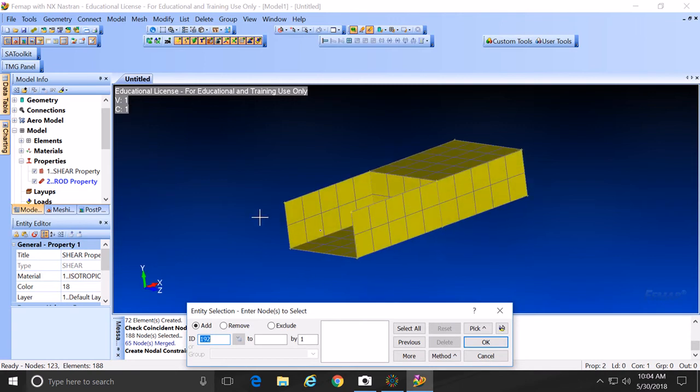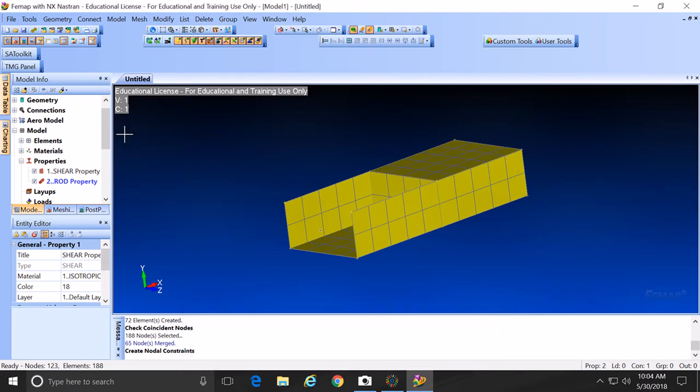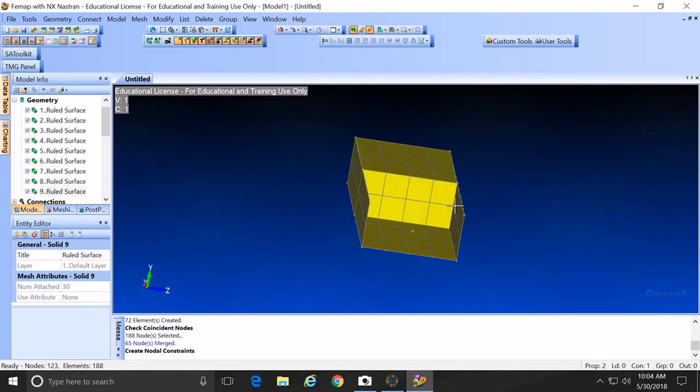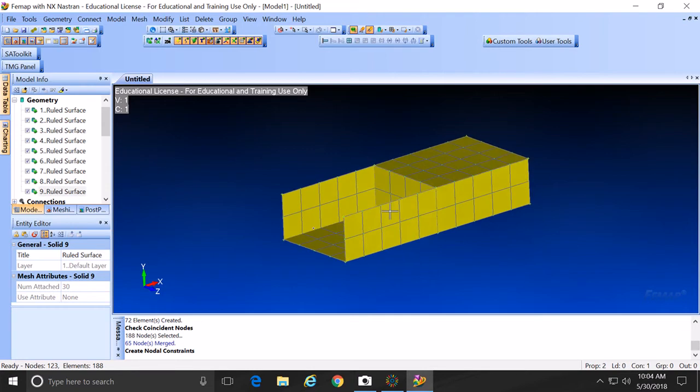And now make sure you select, oops, are there nodes visible here? There are no nodes over here, so. Okay, you see, it did not let us do anything here because we cannot see the nodes, so cancel. Why are there no nodes over here? I guess it has to do with the geometry. Just reactivate all the geometry. Make sure your shear or web fragmentation is selected. They show up here again. I don't know why. Strange. All right, now they show up. When you reactivate the geometry, you see those little green dots over here, those are the nodes.